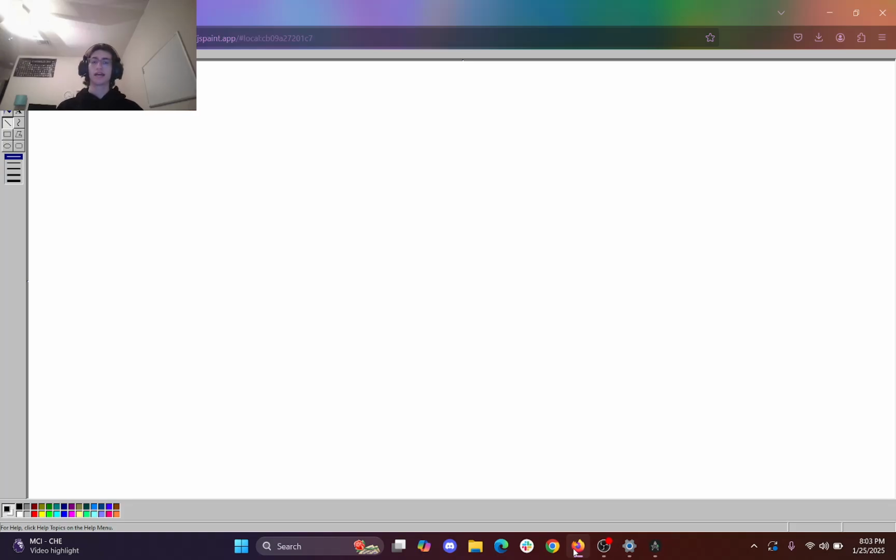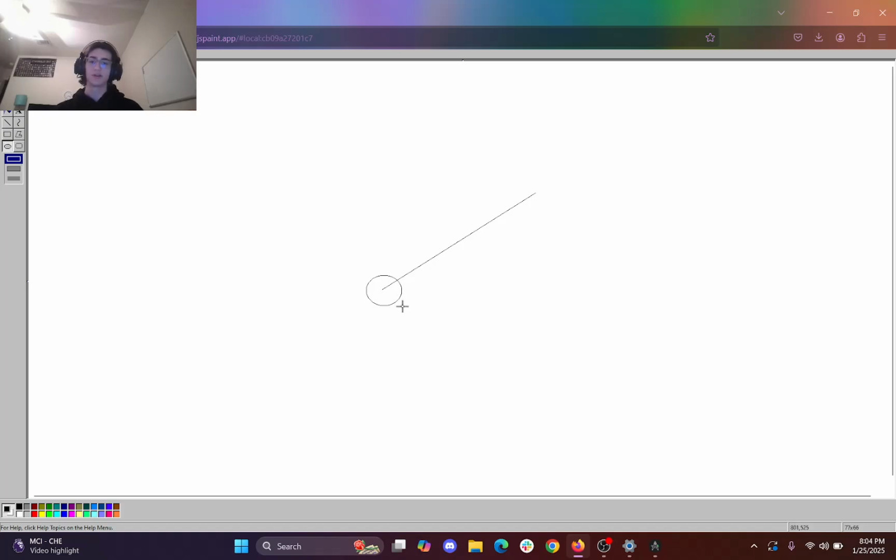Roadrunner generates its path based on point coordinates and tangent angles. In the case of a line, a tangent angle refers to the angle at which that line travels. So if you're familiar with the line2 function in Roadrunner, you'll notice that all you pass into it is an x-coordinate, right? So let's say this is the point 0, 0. Pardon my horrific drawing skills. And this is the x line, like 24. Let's call it 24.